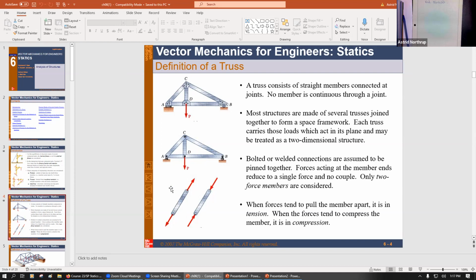So this is a diagram of maybe A to C, and the two possibilities of what can occur. The first shows that structural member in tension because it's being pulled apart, right? The other shows it in compression because it's being pushed together. In a truss, there's really only three choices. Those structural members are going to be in tension, they're going to be in compression, or they're going to be neutral. If they're neutral, they're really not needed.